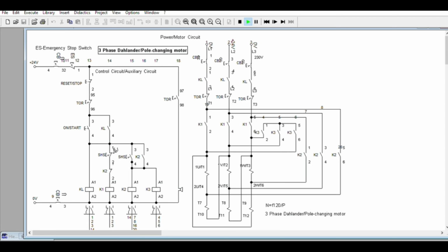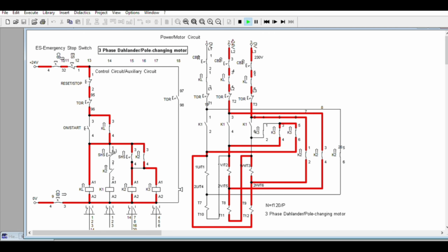There are several ways to make the switch. You can have a toggle selection, a selector switch, as long as it is safe. Again, in some operations, you are going to close this one first, actually for bigger motors, and this one requires some closed transition or some timer operation.